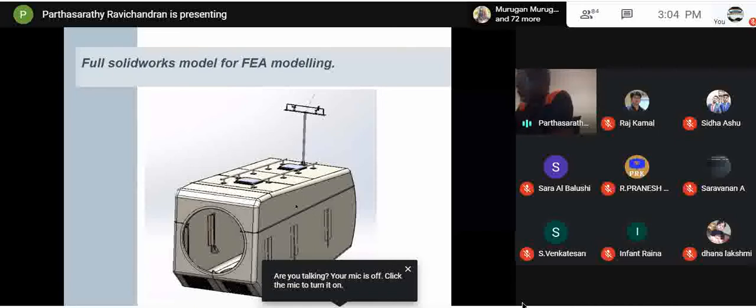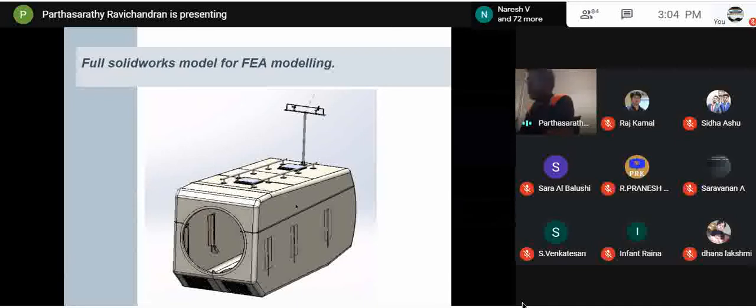So the model, what you see here, is an actual model that has been designed, developed, and this is still running in the site. This was an improved design where you can see that we made sure that the ribs were also part of the nacelle cover itself, so that it's holding a stronger surface, and also we are eliminating the need for having two gussets, rather than having one gusset. I can show you in the next couple of slides how the complete assembly would look like.